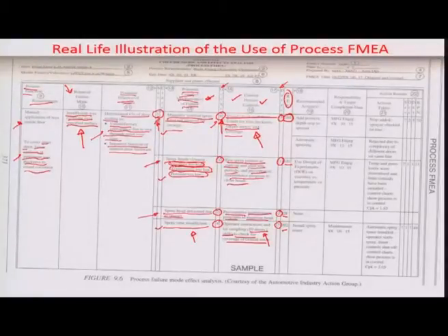So in this particular case, the following actions are recommended by the quality engineer. For the manually inserted spray head not inserted far enough, the engineer suggests a sort of foolproofing, related to adding a positive depth stop to the sprayer. It may be some kind of limit switch which sends a signal to the overall PLC which controls the assembly line.